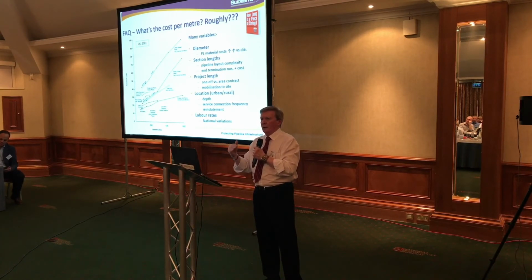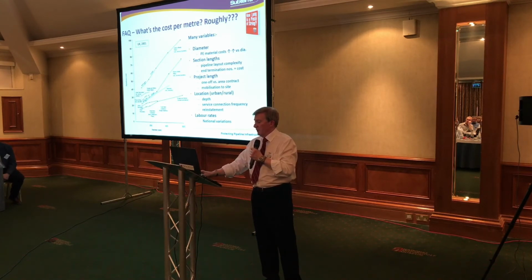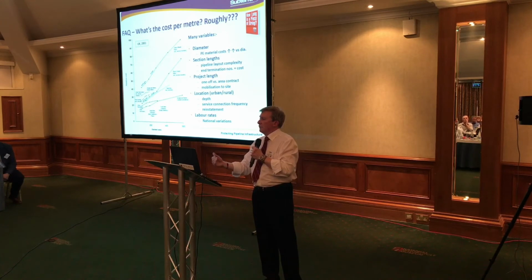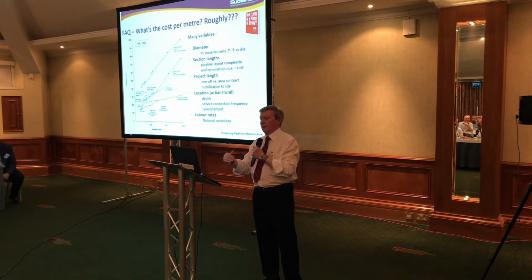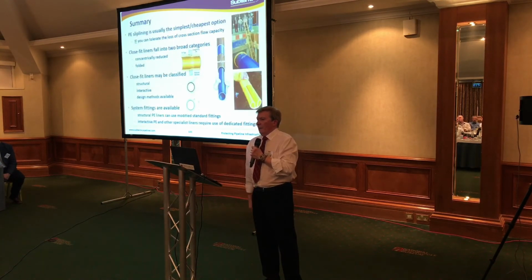We saw earlier that it depends on the frequency of customer service connections. If these are very high in urban situations, there's going to be a lot of additional costs associated with remaking those. And even things like labour rates, national variations can make a significant impact on the competitiveness of the lining technologies. If labour rates are cheap and there's lots of space, in a particular country, it's often more cost-effective just to direct lay.